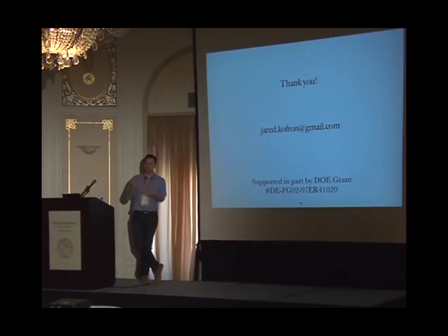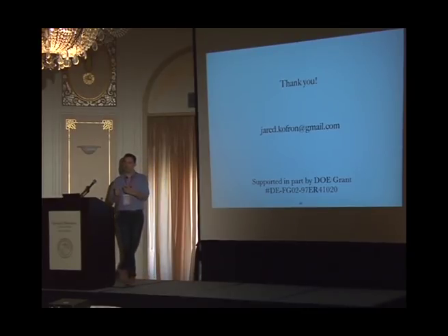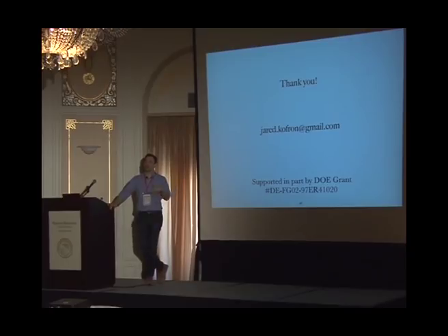And so you have to deal with the bridge. GPIB is essentially an old, very much like token ring way for communicating with instruments. It is a terrible map onto Ethernet, but people did it anyway for some reason. And so there were a lot of implementation details there in terms of getting that logic right in communicating with the bridge. And then there's raw GPIB as well, where you're sending commands over GPIB to instruments to get responses.